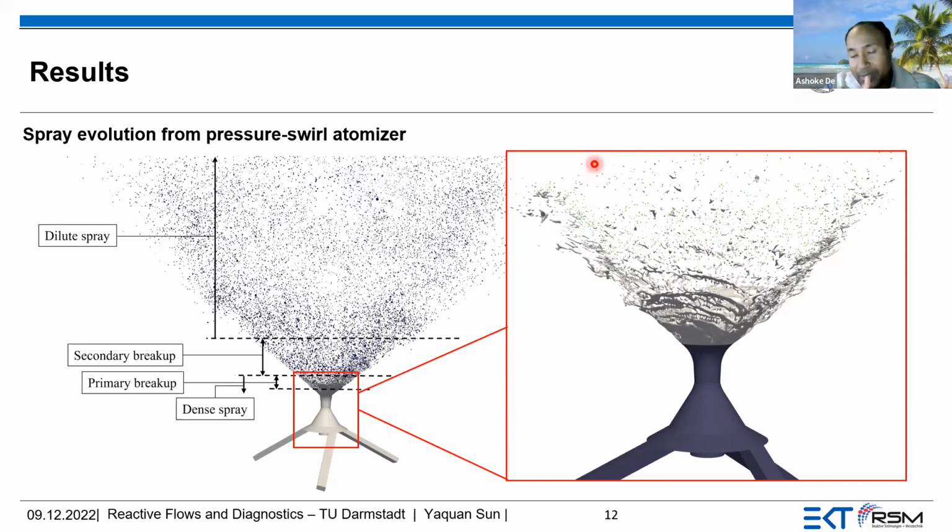Obviously these days CFD complements that and should reduce the downtime, and finally you do PDPA measurements and then characterize the injector. Those mostly come from the original manufacturer, and they provide the range of what it can atomize to and what the size of the particles would be after atomization. Okay, so that's more done at the design level.